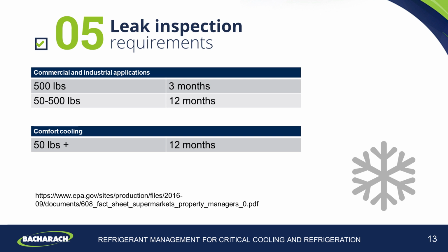So the inspections are required until you can demonstrate that the rolling leak rate is under its threshold for a total of 12 months, which means that if you had one big addition, let's say in January, the leak rate wouldn't drop below that threshold until the following January, and you still then have to demonstrate that it's below that for another 12 months. So ultimately, these inspections are going to be for a 2-year cycle.